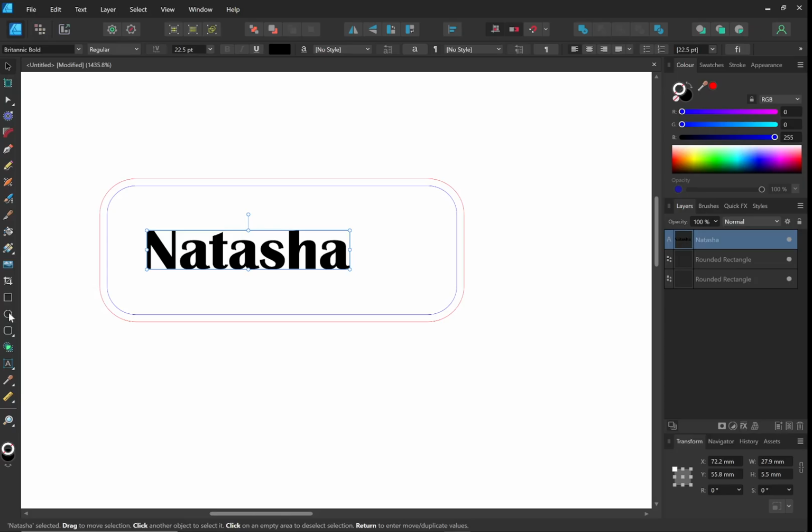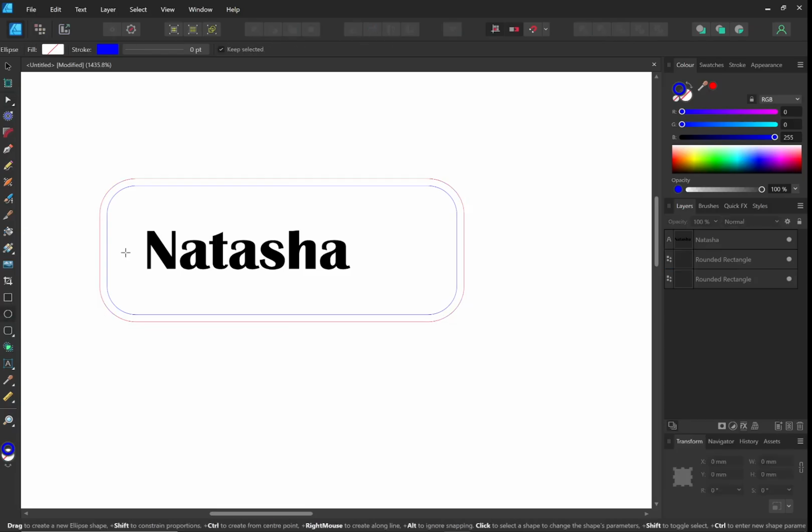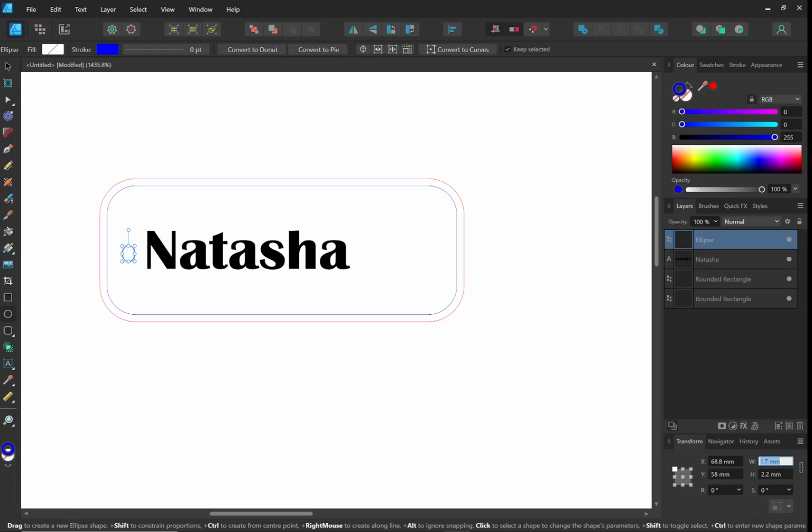So I'm going to use the circle tool, somewhere over here. The size of the hole, not that. Make the hole. We're going to manually make the size of the hole. How big should this hole be? I don't know, maybe 5 mil, maybe 4 mil might be enough. 4 by 4. 4 by 4, so it's quite a big hole actually.